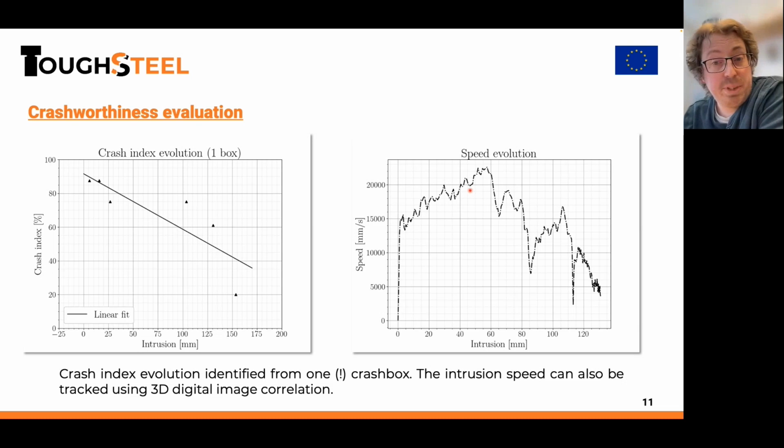And of course, you're also limited to what we see. If the crack is out of view or under a fold or whatever, we might have a problem. So David's results, they're showing that the correlation between fracture toughness and crashworthiness circumvents this problem by ignoring the origin of the crack initiation and focuses on the bulk material behavior, which is essentially what we want.